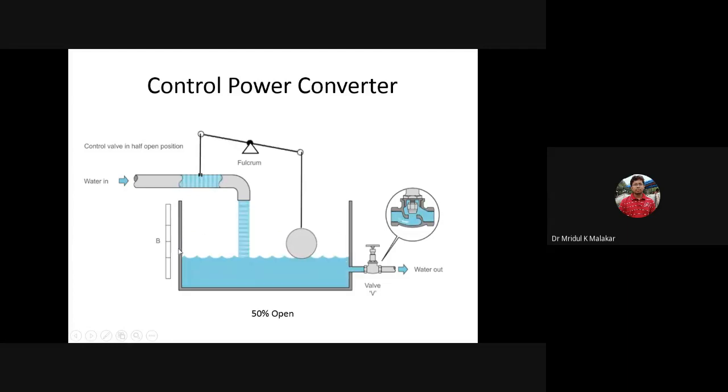So what you have to do is, we read this sensor value, and from the sensor you will get the information, and accordingly there is a control valve here. So it is 50% open, meaning 50% closed valve. Okay, so this controls the output valve. Now see, if control fails, what will happen? Of course, we are designing the control. Anytime we can design the control, but if control fails, what about safety protection? So how to do this?